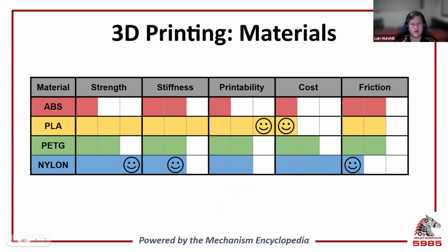So 3D printing is an exceptionally useful tool for power transmission. It allows you to print components so that you don't have to purchase them, which significantly reduces lead time and part cost, especially for us Australian teams. With 3D printing, you're able to print gears as well as pulleys for both belts, polycord, and polybelt. You should not print sprockets, as chain is usually used in high-load applications that printed parts are just not suited for. When printing power transmission components, you must be sure to design your parts correctly and print your parts out of the right materials and with the right settings.